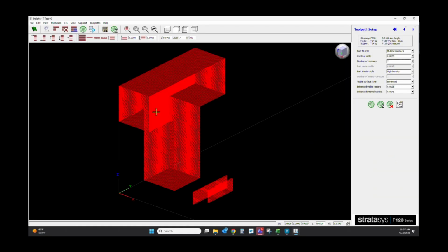So basically all I did is just generate toolpaths. I brought that file that was in GrabCAD Print over and just sliced it and generated toolpaths just so we can kind of see what's going on. But with the toolpath adjustments, you can see that there's not a ton of adjustability here. High density sparse is our only option for infill. And we can change the infill raster width. So that is our bead width going 45-degree angle across the part.